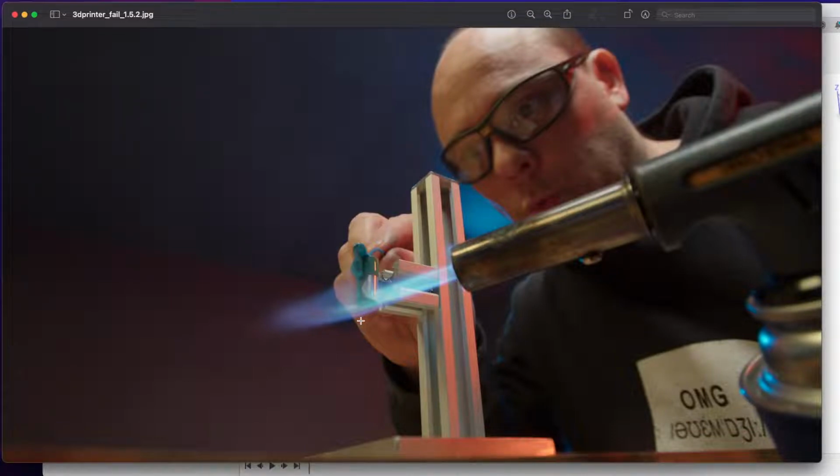If this fails, everything else will fail. Everything else is just to support and make this specific process useful, and that is the melting of plastic, making a material soft or liquid by heating it, and then generating a pressure differential inside the melting chamber, so it will take the path of least resistance, which is through the nozzle.